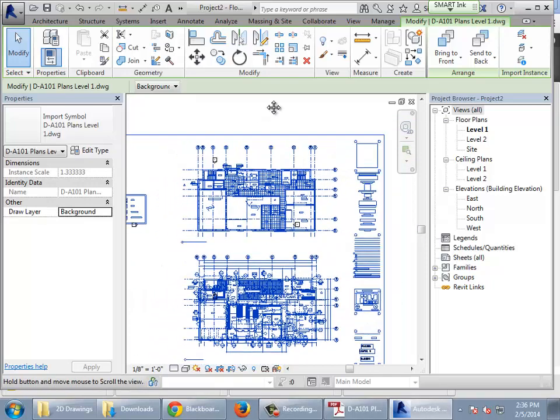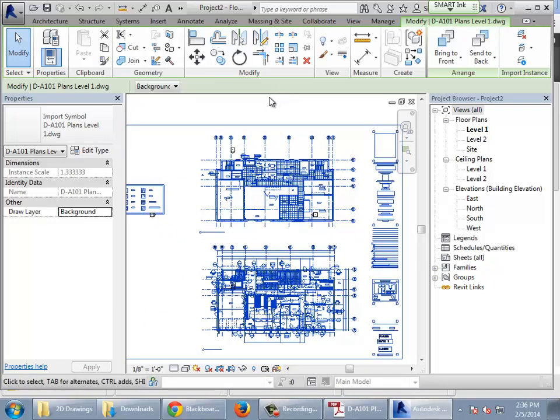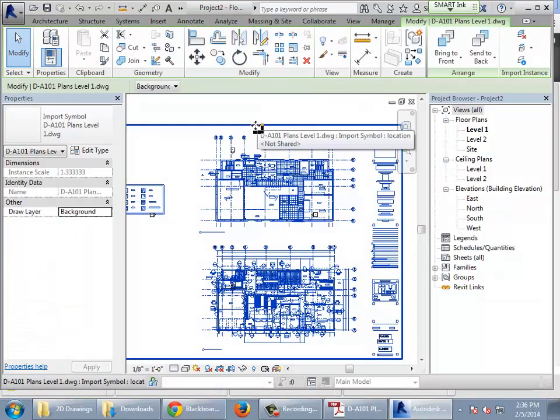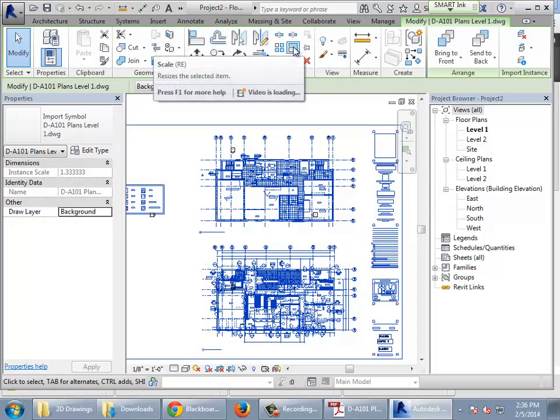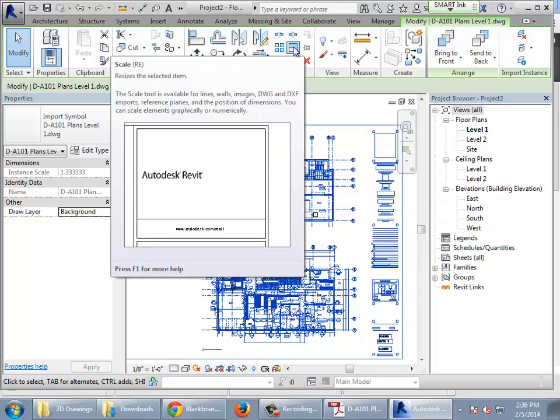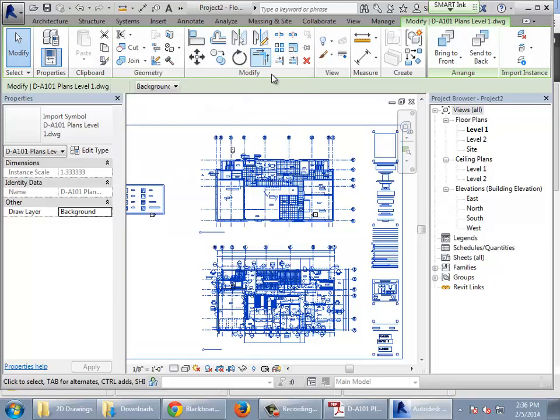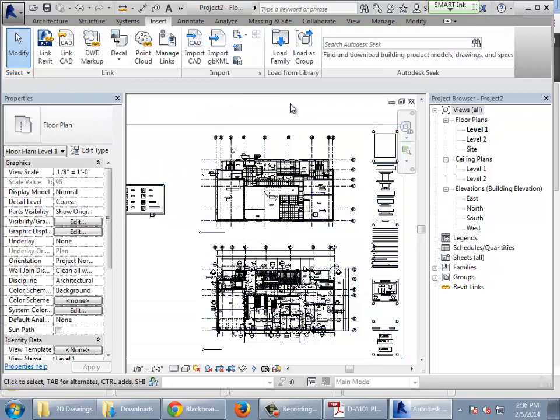Okay, and the message is that you can't rotate a pinned element? Yeah. Try this. Go ahead and click on it, and see if you have something in here that looks like a pin or an unpin, because that'll unpin it. Let's see if that'll do it. So is it pinned, or what do you think? Yeah.